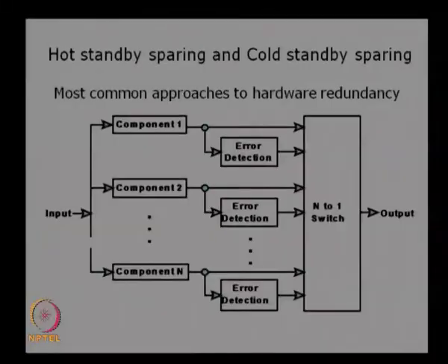But of course, the system can actually identify that there is a power failure, and that data will be sent to the other processors, so the mode will change, the brightness of the display will change, and all those things will take place within the system, because an error has already been declared, and all the actions for tolerating that particular error will take place after that. That is why hot standby helps to reduce the time delay in taking over or changing the outputs. Here you can take component 1 as an external power supply and component 2 as the battery source in the laptop.